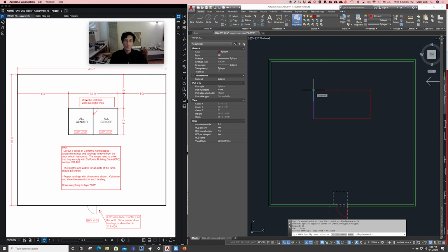I'm going to do it by snapping. Again, I'm not going to use numerical means to draw. I'm going to use graphical means and let AutoCAD do the work for me to put it into place, because I know that if I snap to midpoints and endpoints, it's going to be right on, because AutoCAD's not going to lie to me as far as those go. But if I happen to enter a fraction incorrectly, or if it's a 32nd of an inch off, or even a 256th of an inch off, it'll be that far off. It's not going to be precise.